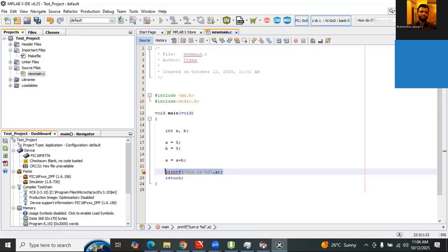Probably for 13, it means 1101. Right. The total LEDs that you have, for example, if you have connected 8 LEDs to that port, only 3 LEDs will glow. The very first one will glow, the second one will not glow, third and fourth will glow. That's all. Remaining will be in off state. Agree? Yes, sir. Right. So it will be converted to bits.